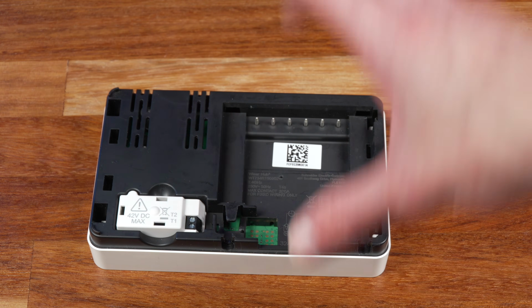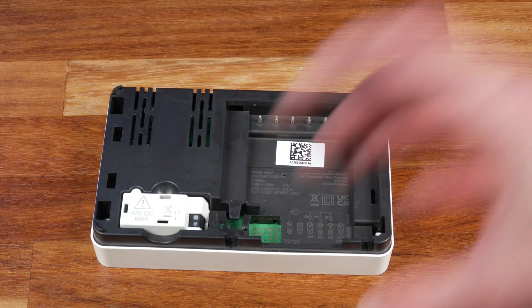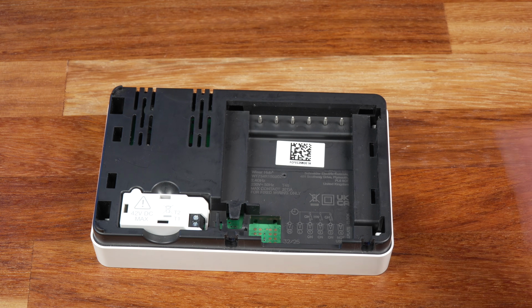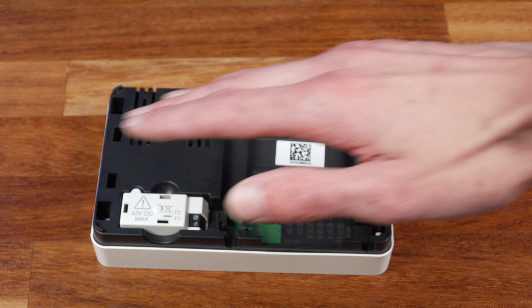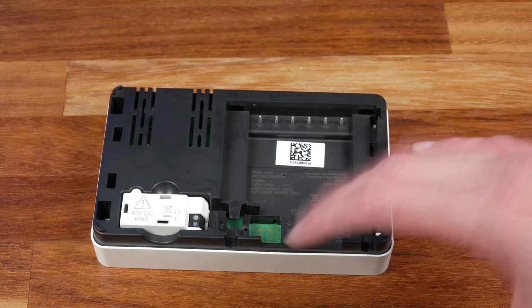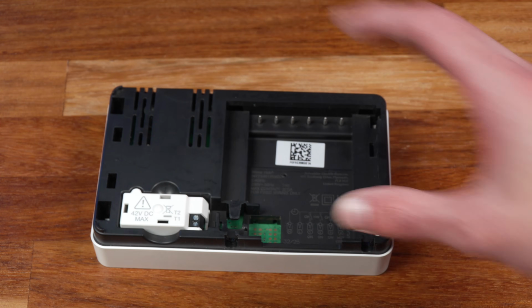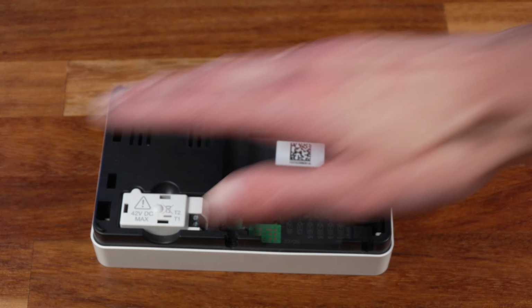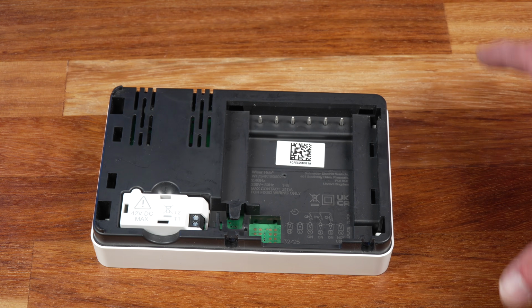OpenTherm, on the other hand, is a digital connection between the thermostat and your boiler, and it allows the thermostat to request a particular flow temperature. So if the Wiser hub senses that the rooms are really, really cold and need a lot of heat, it can tell your boiler to get really, really hot and pump out a lot of heat. Then if the rooms are almost at the set point, maybe the set point's 20 degrees and the rooms are like 19.5 degrees, the Wiser hub can tell the boiler to drop its temperature down and maybe only put out water at about 40 degrees, 35 degrees. And that can really help you maintain a really nice constant indoor temperature,